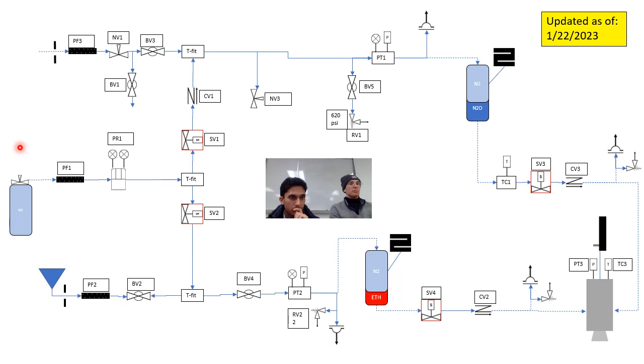Okay, so we screw our nitrogen flex hose, which is connected to our nitrogen bottle, into particulate filter 1, PF1. Then we open the bottle, and so now we pressurize to whatever the bottle pressure is, which could be, I think, between 1,000 and maybe even more than 2,000 psi, up until PR1, pressure regulator 1.